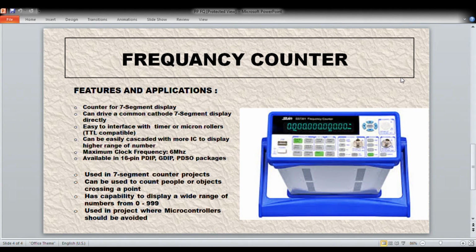Now I will talk about the applications of the frequency counter. The frequency counter can accurately measure the frequency, the time interval, the phase, and the event count, etc. The frequency counter function is designed according to its application. The most common application is to determine the characteristics of transmitters and receivers. Other applications include the computer field, which uses high performance clocking, data communication, microprocessors, and displays. Performance requirements are not high in these areas of application.